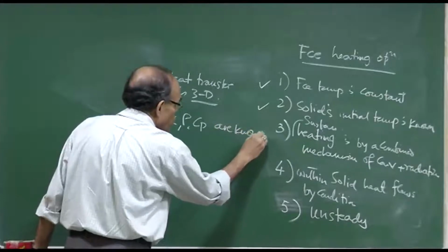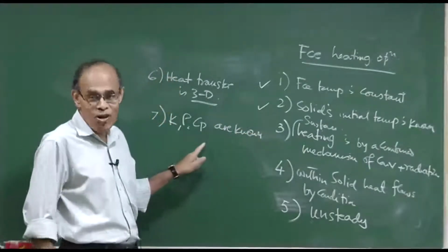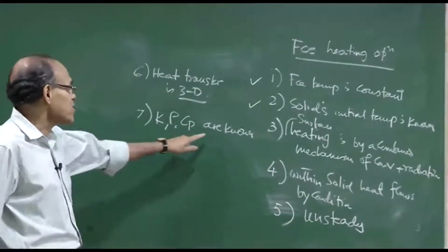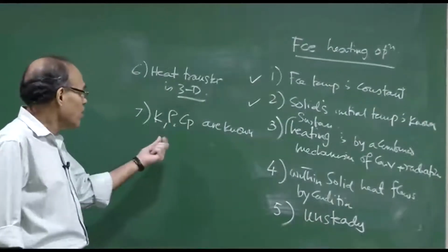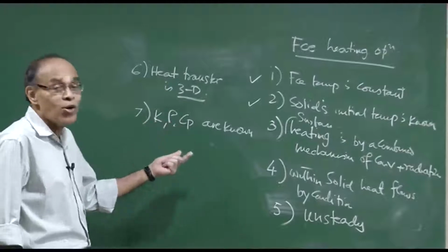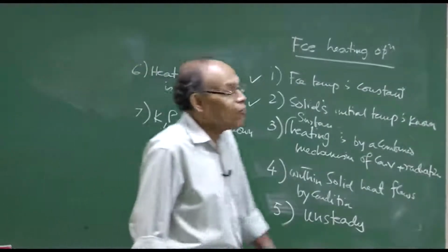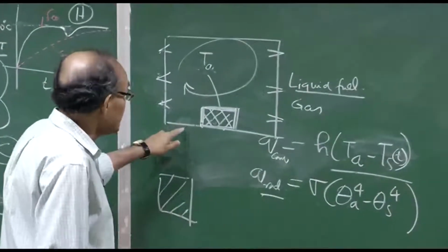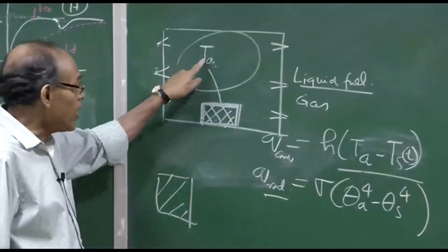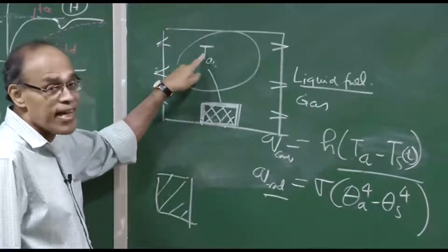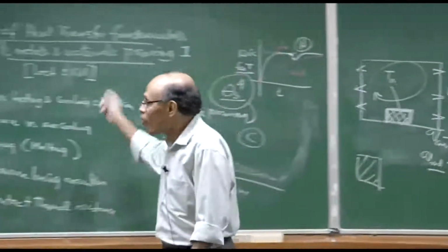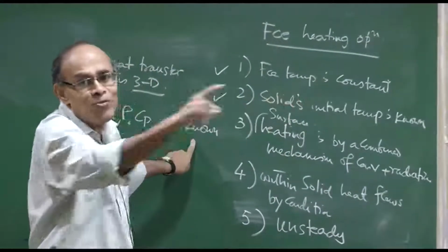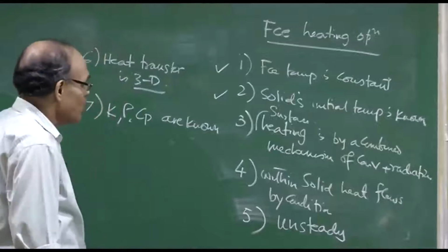You have to have an equation of state in order to understand how these vary with temperature and so forth. If you are not so fussy, you can work on the basis of a constant thermal conductivity and specific heat, which are representative of the film temperature. We solved film temperature in one example earlier: if you know TA and the initial temperature of 25 degrees centigrade, you take an average temperature and evaluate the properties at that, and this will depend on whether it is a steel sample, a copper sample, an aluminum sample, and so on.